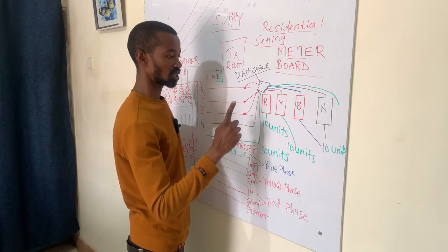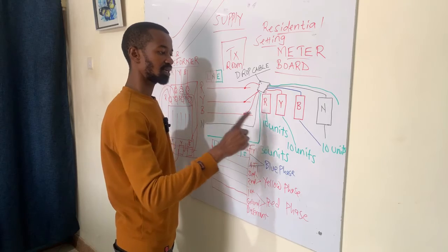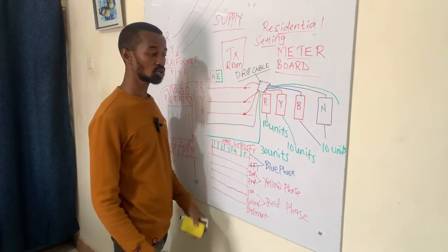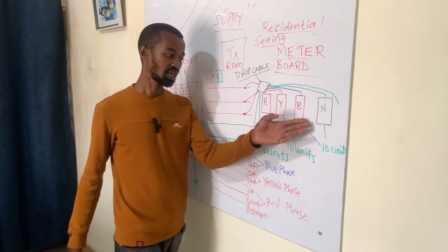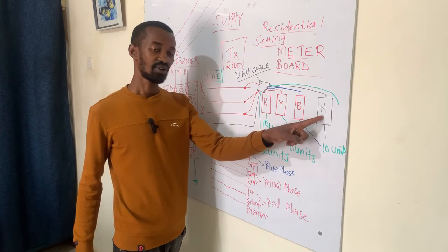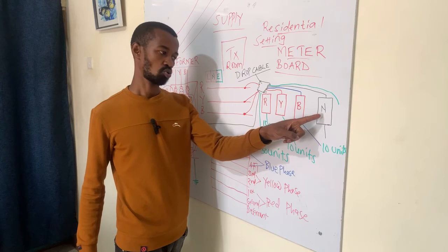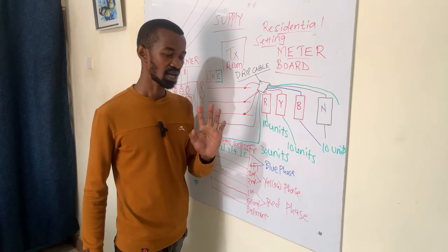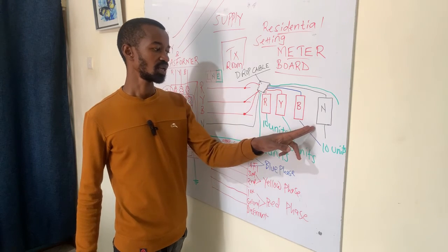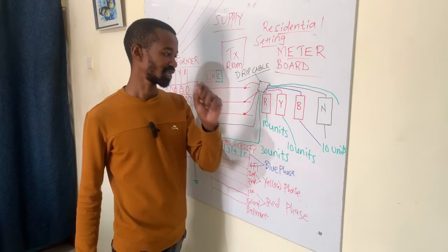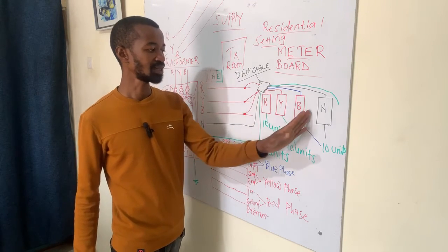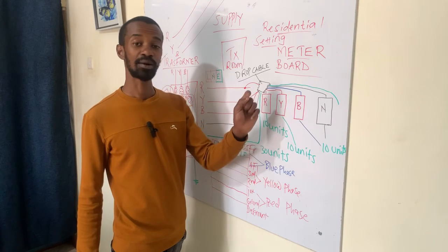You cannot take the neutral connection lightly, because even as our resident top engineer Clemax knows, if you have a loose connection at the neutral or at the return, there is a problem, because electricity will not find a good, safe path to return to the source.